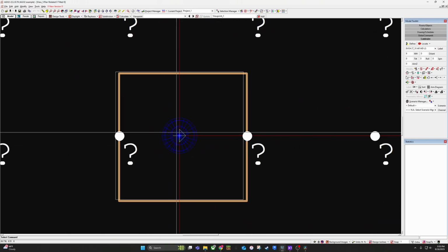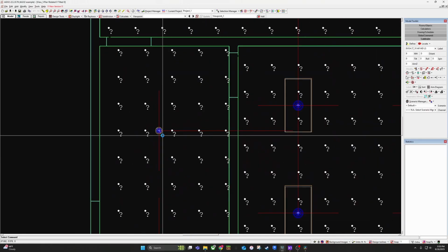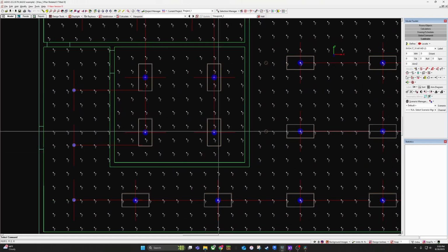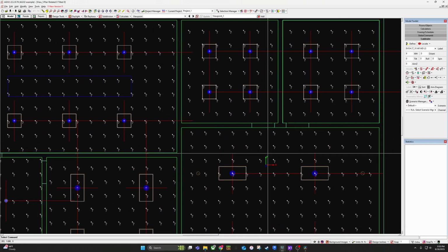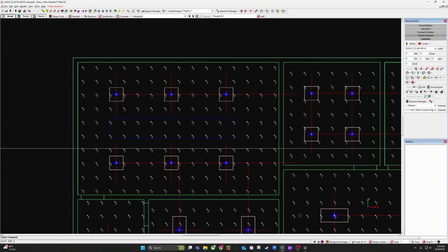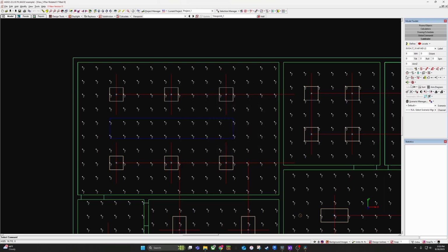So it shows that the distribution here is straight down for these guys, as well as this. Usually whenever you have lights that are throwing in a certain direction, it's always good to make sure that you're aiming the correct way by turning on the candela curves. But for now, let's turn them off because they do bog down the file a little bit.